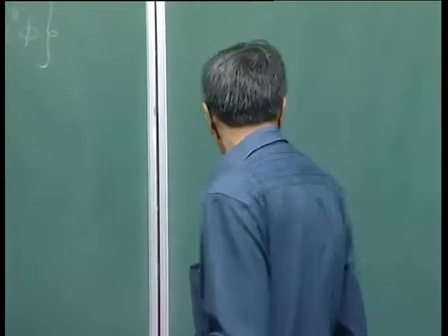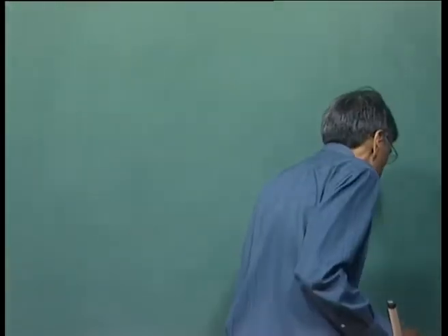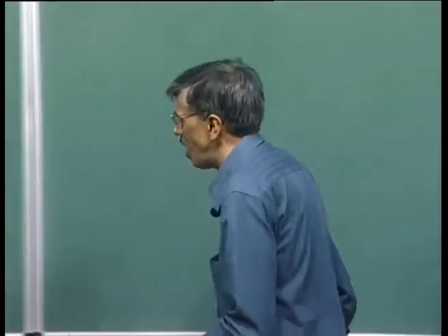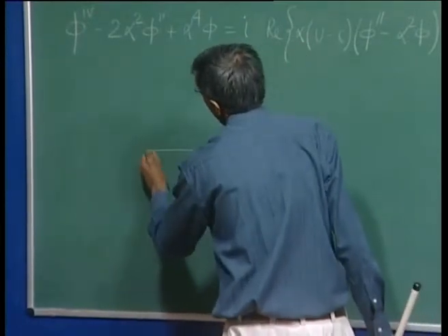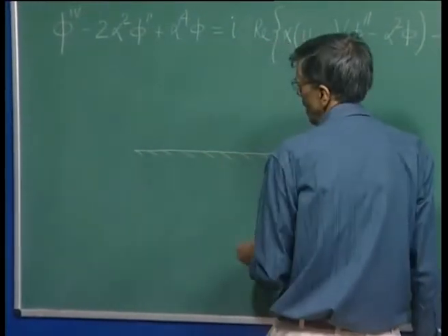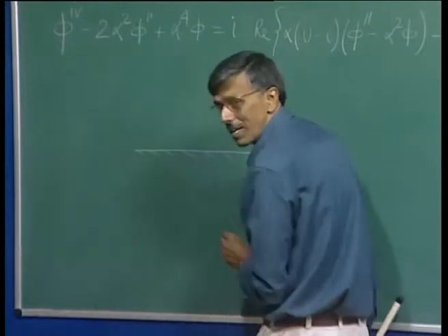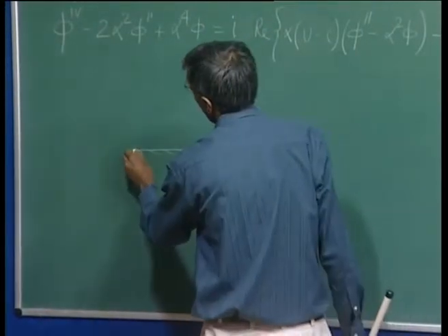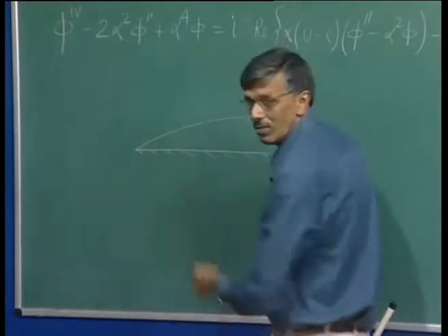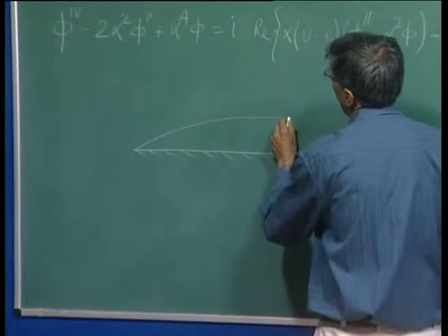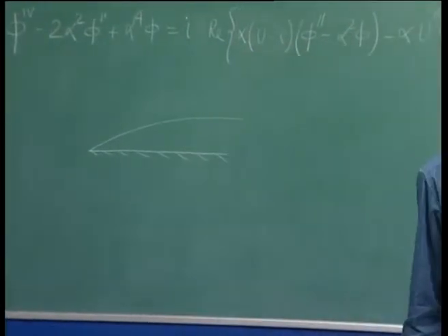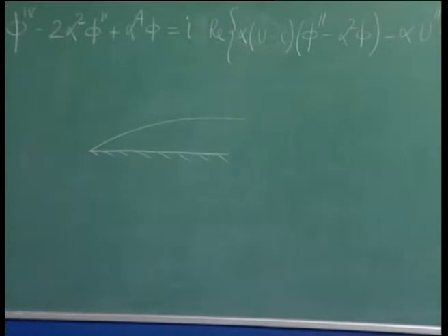Okay. So, if we look at the schematic a bit, this is how it should look: we have a flat plate here, over which a boundary layer develops. Since the flat plate has a very sharp leading edge, we will have a boundary layer originating from there. Now, what we want to do is make use of this Orr-Sommerfeld equation, and I would try to tell you how we got this.